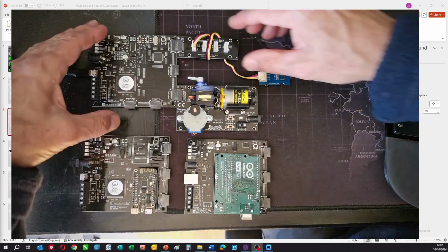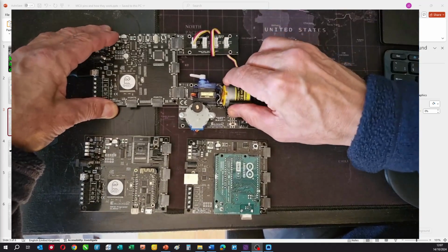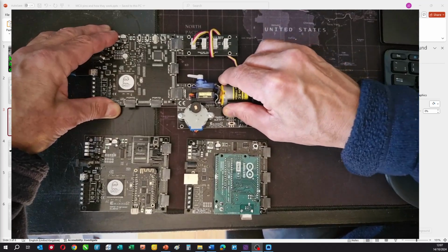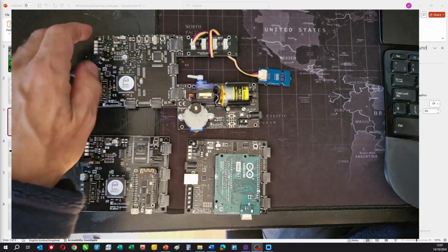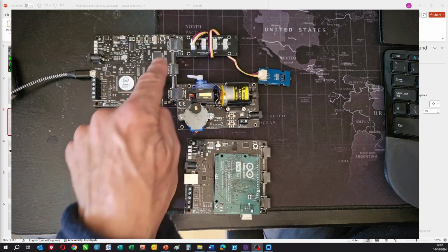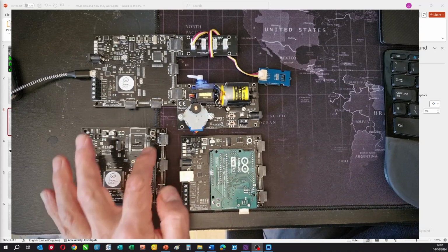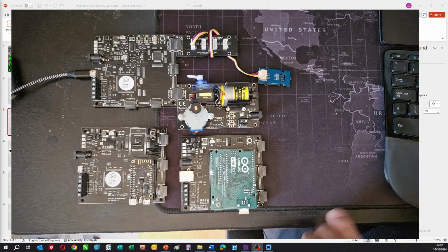And the idea behind eBlocks is you can quickly connect and disconnect peripherals, and these are 14-way fast connectors, so power and ground as well as the 8 bits of each port is there. And normally we present pins in collections of 8. For the PIC micro there's ports A, B, C, D and E. For the Lowlin there's A, B and C. And the Arduino is slightly different because the terminology in Arduino is slightly different.